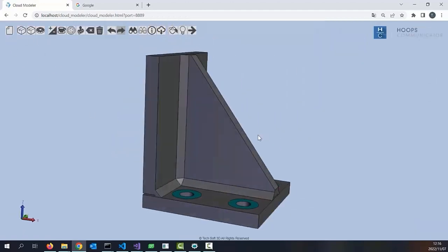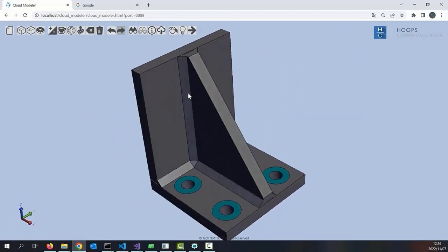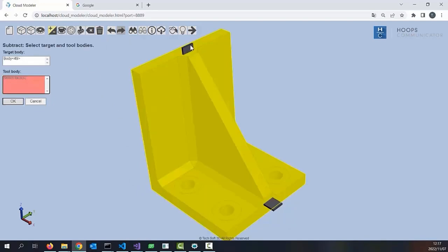Since Parasolid is running on the server, and we have a full history of all the modifications made to this model, we can simply utilize Parasolid's built-in session handling to undo the Boolean subtraction that we did earlier. Now we can see the location that will need a design change. We'll delete the extra element and rerun the Boolean subtraction to represent a groove weld as opposed to a fillet weld.